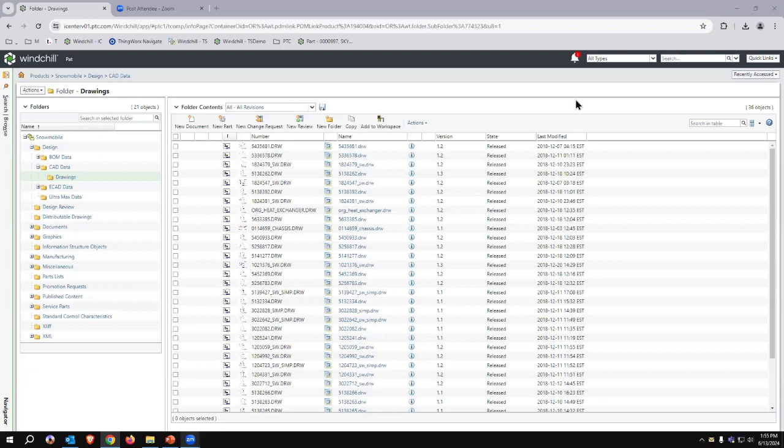The viewer supports some additional functionality like quick view and things like this in later versions. But if you're using previous versions of Windchill, you can actually use higher versions of Creo View. So if you're running Windchill 12 or Windchill 11, you can actually use Creo View 10.1, which has been released with Windchill 13, to view models in your Windchill as well. So I haven't found a problem with that.